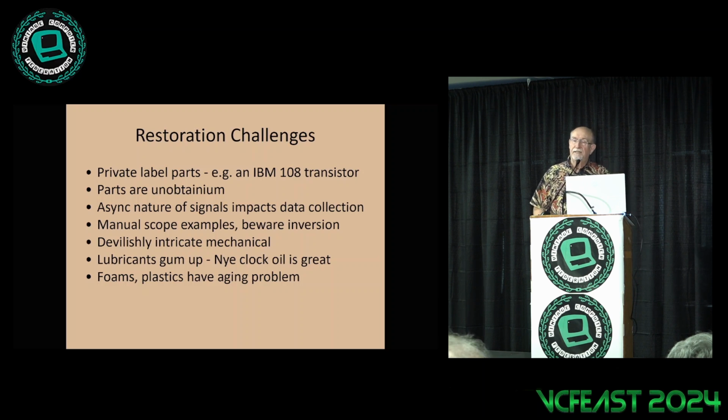Now, the nice thing is, at this level of technology, it's easy, because the SLT and the SMS before it use discrete transistors, discrete diodes, resistors, capacitors. You can look at every signal. You can replace it. If you wanted to make a replacement for one of those little modules on a card, with modern surface mount transistors and diodes, you can fit all of those on a little circuit board the exact same size. So it's very easy to design and make whatever you need to replace it. So that is one advantage.